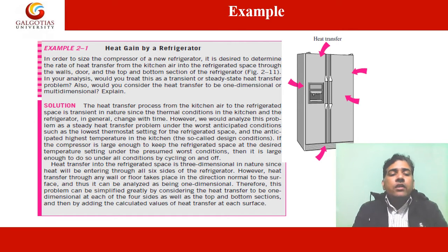So the heat transfer into the refrigerated space is three-dimensional in nature, since the heat will be entering through all six sides of the refrigerator. However, heat transfer through any wall or floor takes place in the direction normal to the surface. Thus, it can be analyzed as being one-dimensional.